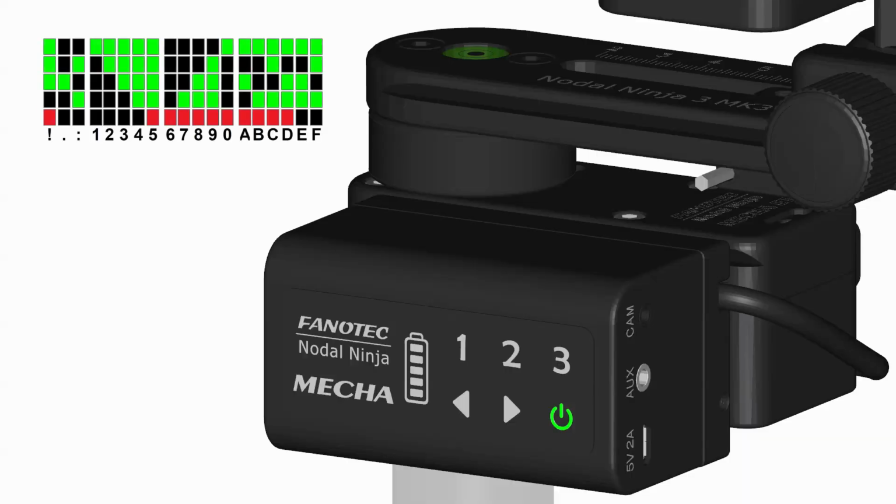Let's analyze now the C1 and C2 controllers separately. On the C1 controller, at the end of the startup sequence, the LEDs display the last octet of the IP address, beginning with a dot, if MECHA has previously been connected to a network. Alternatively, you can use code 321 when MECHA is idle. As an example, if the LEDs show .100, the full IP address is 192.168.2.100.